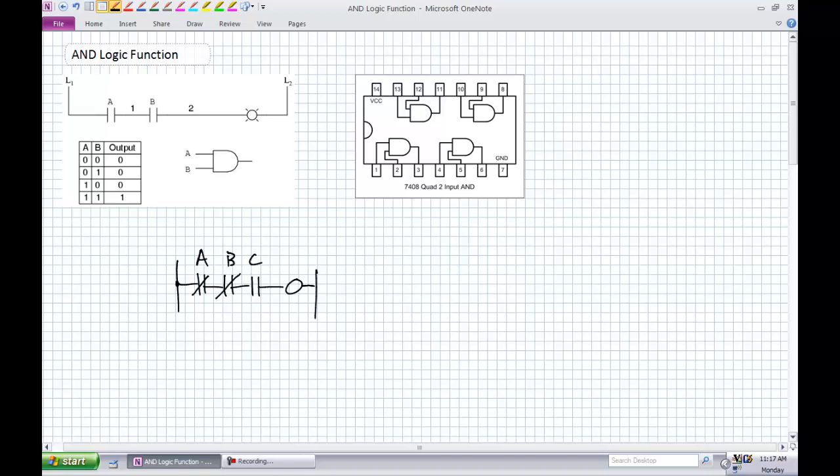Nope. Okay, so my rocket ship is not going to blast off. Okay, now there is enough fuel, blast off. That thing lights up. So it's a safety chain. Additionally, like I said earlier, any one of those conditions can turn it off. So A, B, and C, can't remember what the earlier one was. Pressure, fuel all set, and temperature. All of a sudden the motor overheats, turns the whole thing off.